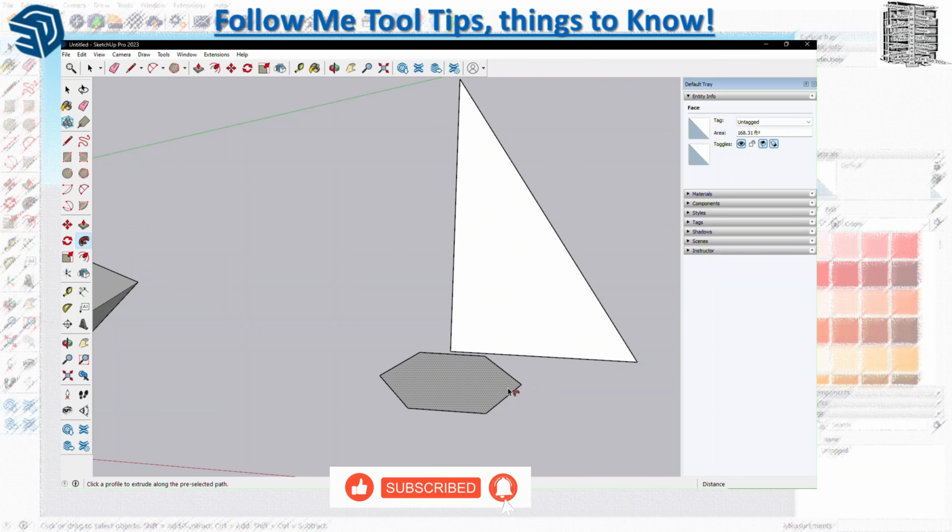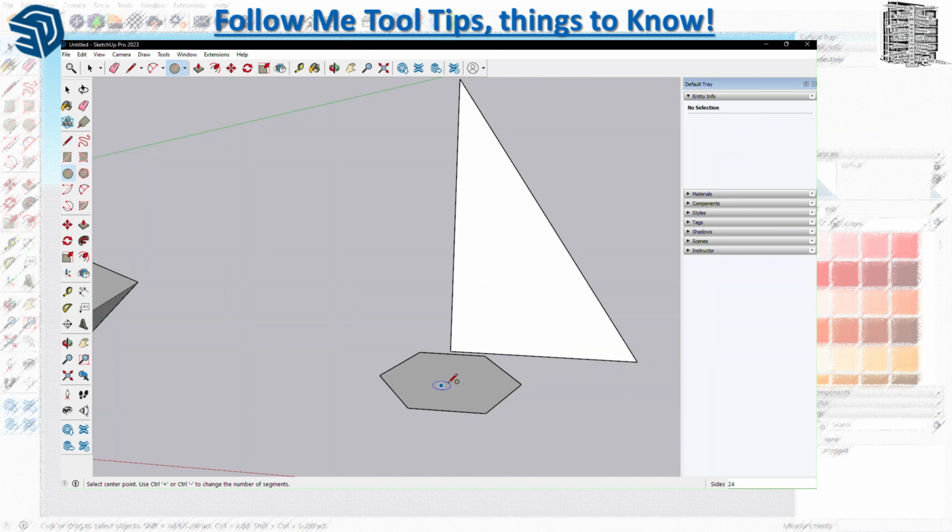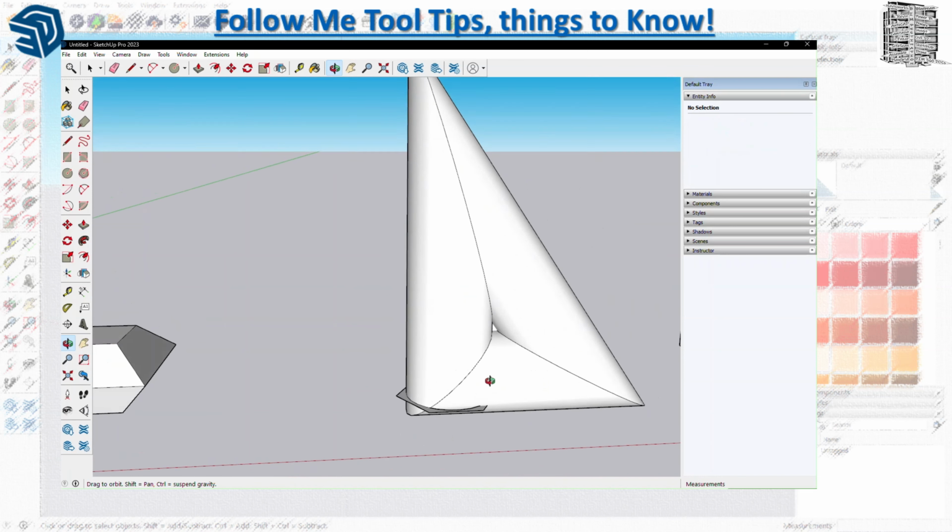So we know that we can go alongside all the edges on the different sides. We know that if we select the surface, it's going to follow that. Right now I just want to add a circle to this polygon that I have. I'm going to get the center of it, and let's just try it this way. See how you can create complex geometry with just the Follow Me tool and a simple shape. Right now you can see how this is going to look, right?